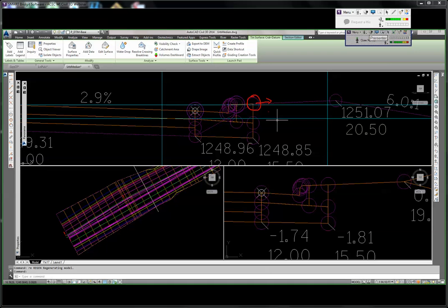If you do it this way, you do need to come down. You first of all need to give this point here a unique code, P3, P4, something that's unique. And then also you have to tell this code here not to be optional, not to be turned on. I don't want to use that particular code to build my surface. What that's going to do is force it to start here, come to this point, and then, and again, I'm exaggerating this greatly so you can see it. It will then go up to this point and continue on from there. If this distance is very small, you'll never see that kind of slope, and everything will look appropriate.